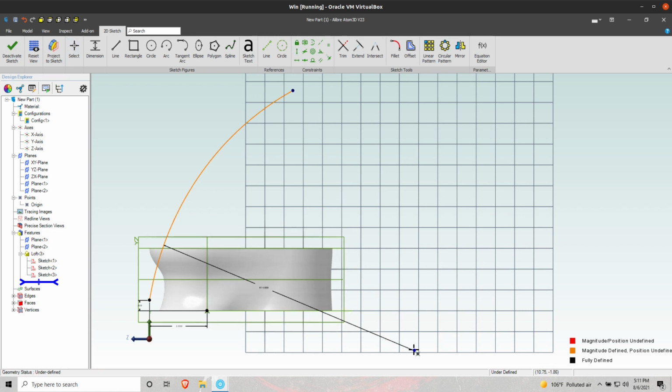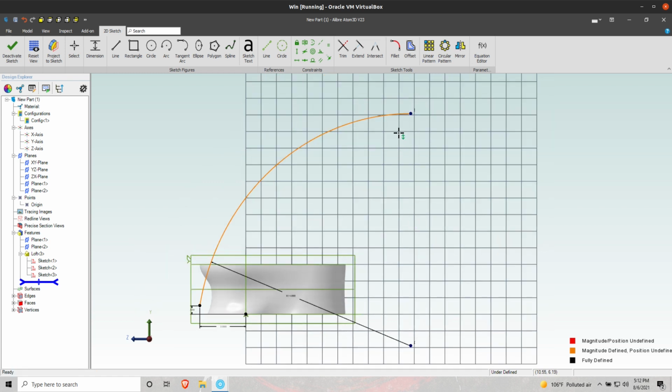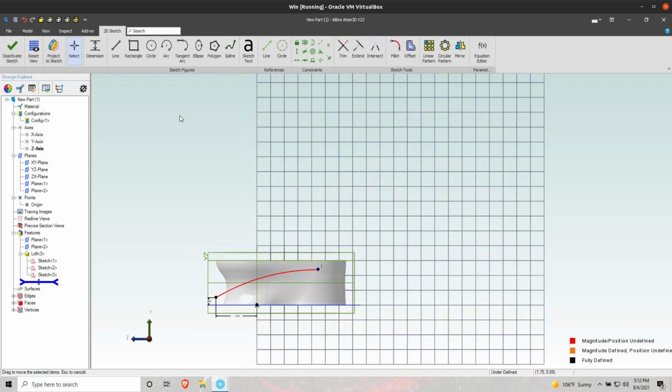Let's go with an arc that is vertical to its center point so that it ends on horizontal. And you know what? I want to reposition this, so I'm just going to get rid of my 14-inch dimension here. And let's position this a bit more like that. That's better. Still ends with that little vertical constraint, so I'll re-add my dimension here at 14.